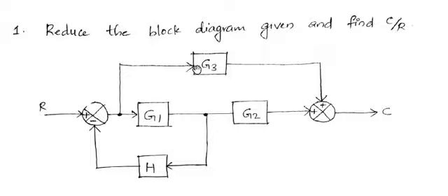So the signal Y, which is the output of the summing point, goes to G3. That is the original case. But what will happen if I shift this branch point ahead of G1? Let's imagine that this branch point is now here. Then what is the signal that is going to G3?